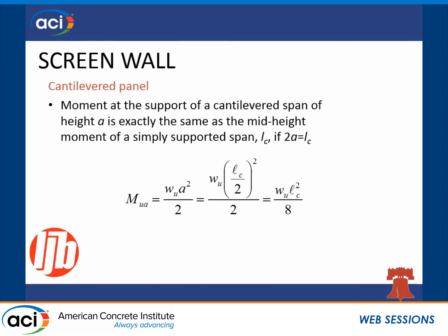I say basically the same calculations because that's true from the strength perspective. But from a deflection perspective, you have to use judgment about the serviceability deflection that you want to consider for a screen wall as opposed to a building element.